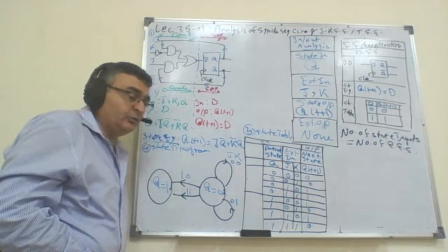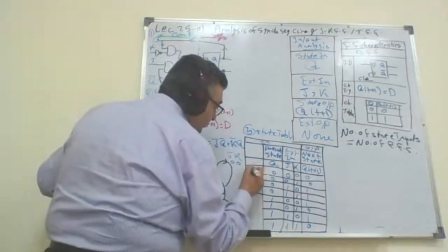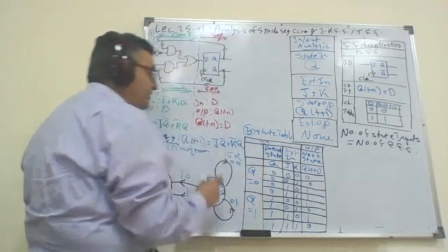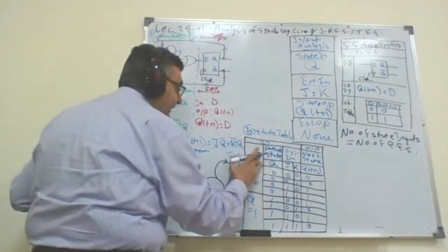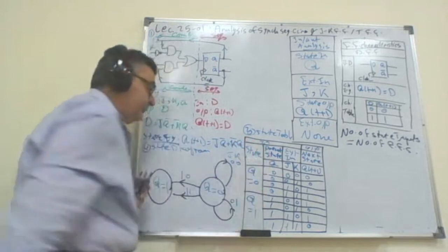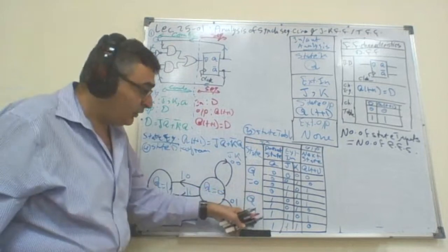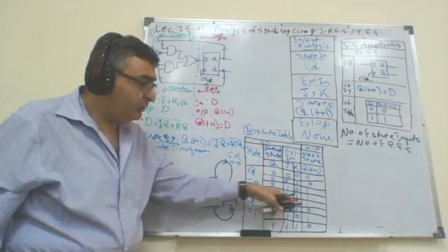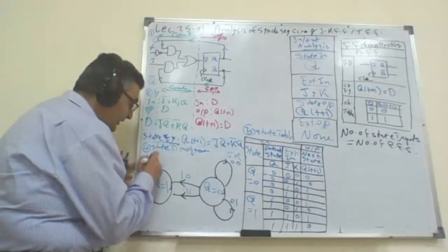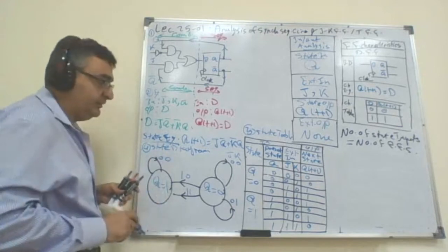I will repeat all of this for state 1. Here, in the layout of the table, Q equals 0 here, Q equals 1 here. This is actually representing the state. Right. I am in state 1, and JK equals 0, 0. Where should I go? I have to stay in state 1. 0, 0 here, staying in my state.